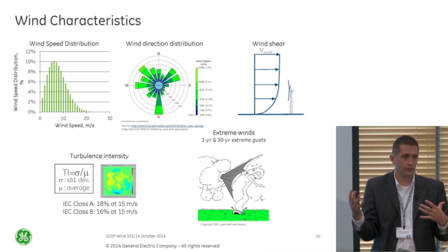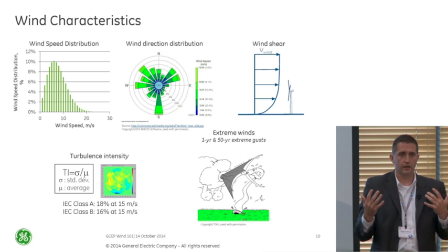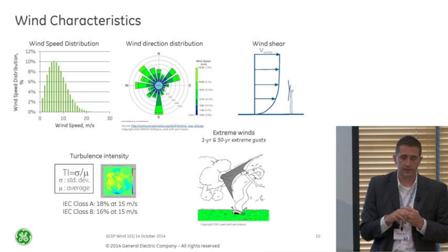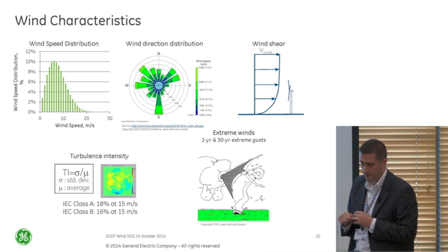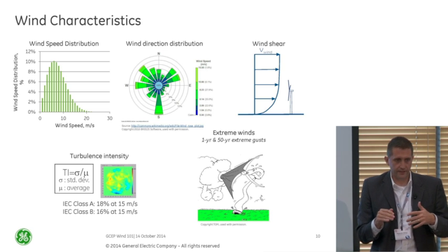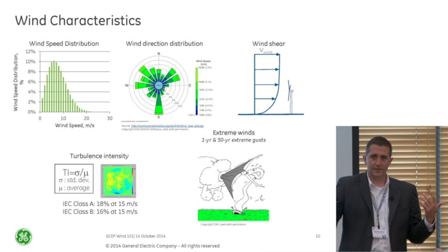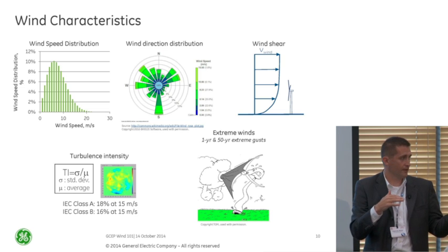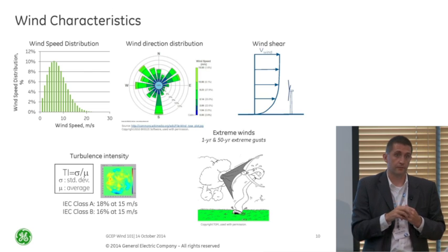Even though you might have a great wind resource, if it's shifting around quite a bit, specifically on really short time scales, it becomes a tough thing for some of these wind turbines to handle. Another thing is that, and you probably know this if you went to a tall building sometimes, it's always windier at the top of a tall building. So there's a thing called wind shear. If you stand around outside, as you go up, it gets windier.